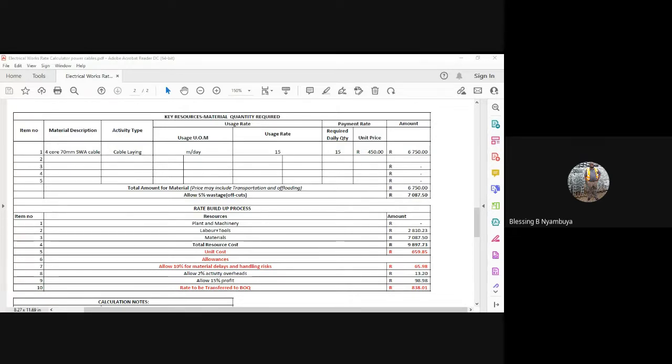And the registered electrician would come and do the QA process to check if all the lugs have been lugged correctly, and do the measurements, earth resistance measurements, the earth leakage test. I'm talking of basic things here. There are other tests that can be done, but assistant electricians can act as an electrician, but an electrician will not be able to act as an assistant.